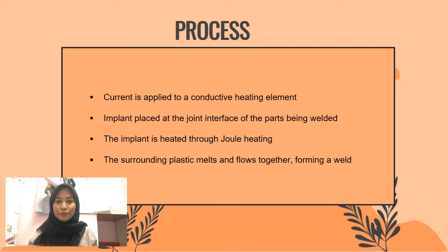The process of resistance welding. Firstly, the current is applied to a conductive heating element. Second, the implant is placed at the joint interface of the parts being welded. Next, the implant is heated through Joule heating. And lastly, the surrounding plastic melts and flows together, forming a weld.